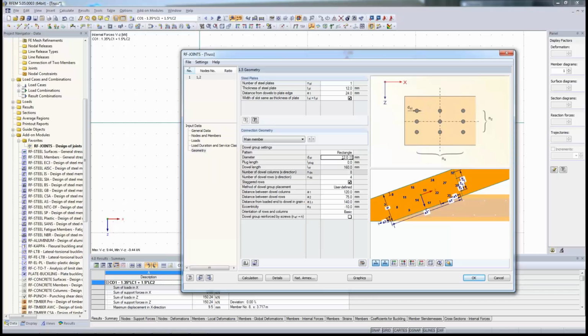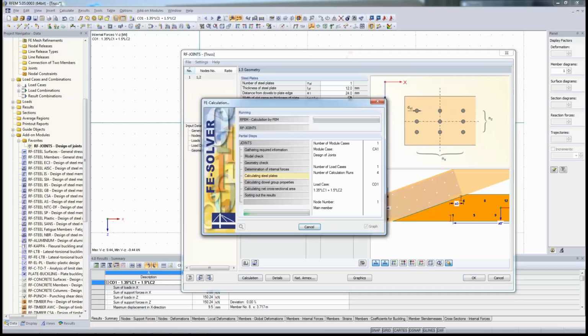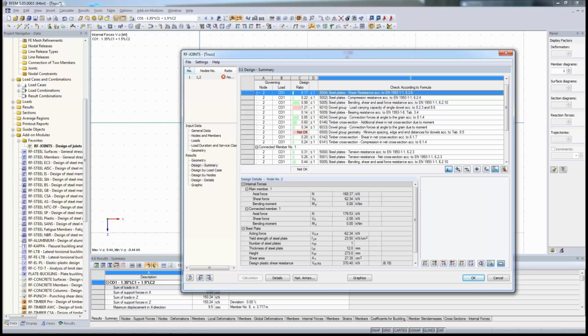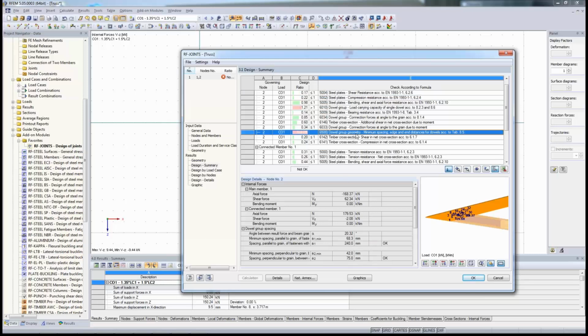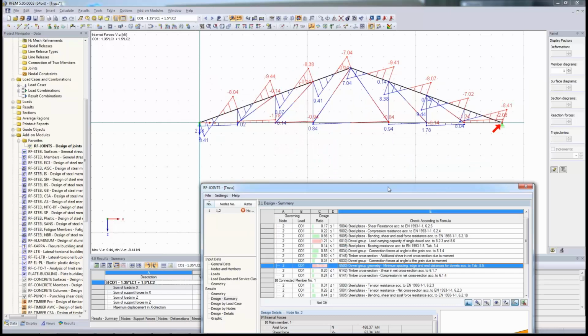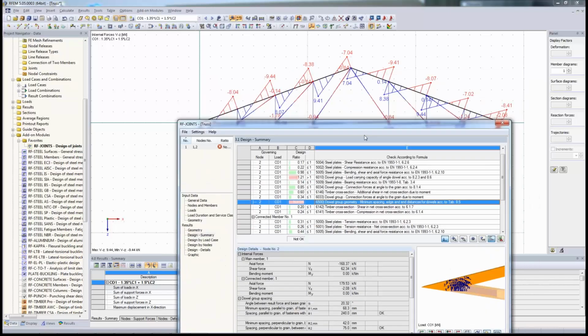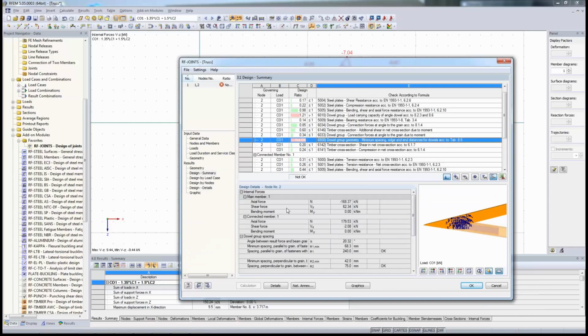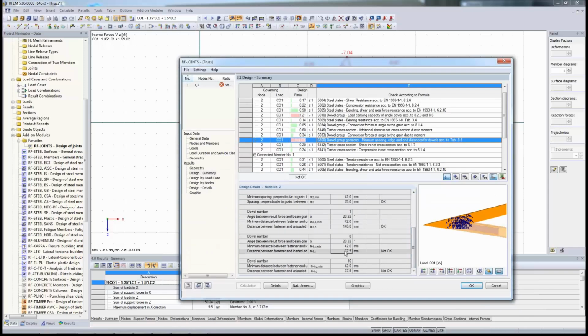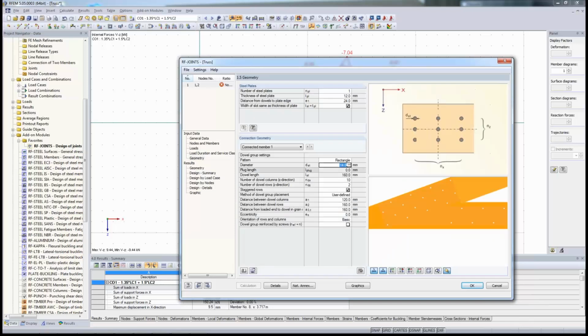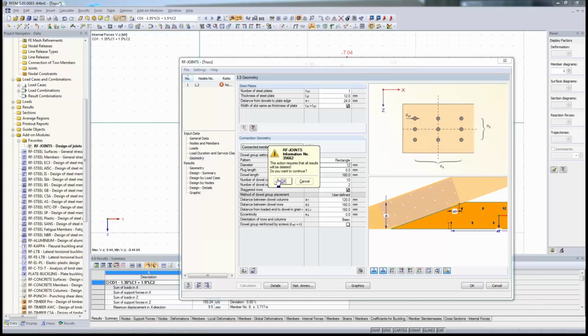So for now, what else can I do? Maybe if I just have overloading in the dowels, which is the case right now, choose a higher diameter for this situation. So then I get some problem with the limit distance. Okay, and where do I have it? In A4T direction. Okay, better to go with 12 millimeter, I think.